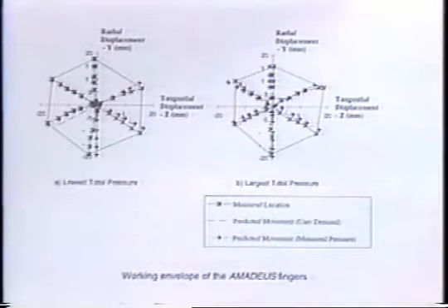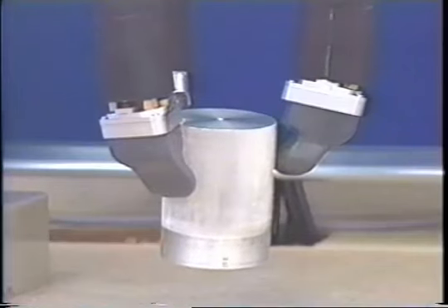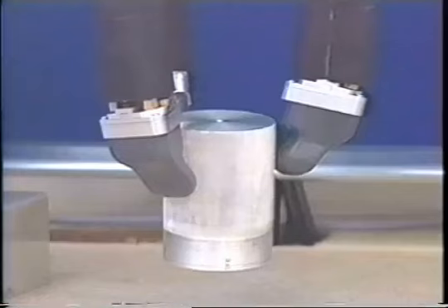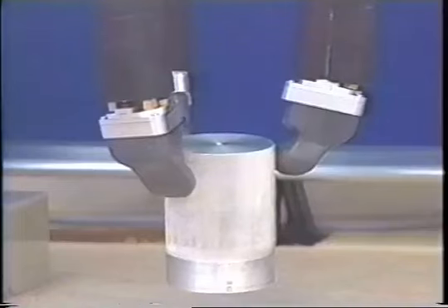Low-level control of force and position uses a task function approach with a calibrated finger model to estimate unconstrained motion. Medium-level control coordinates finger and knuckle actuators to control grasping. Data from the slip sensors is used to reactively trigger changes in grasp forces. Slipping can thus be prevented or deliberately controlled.